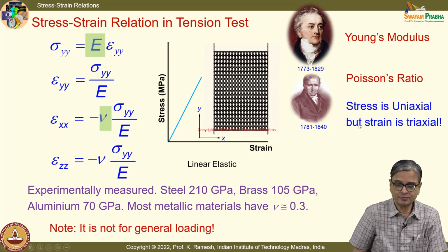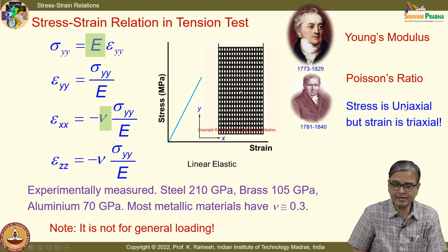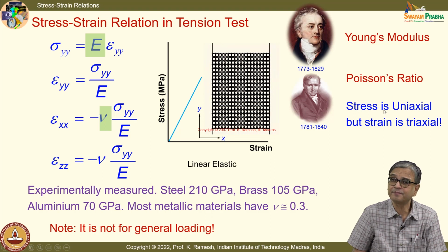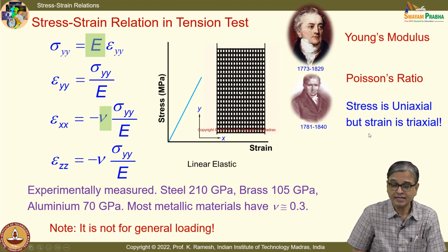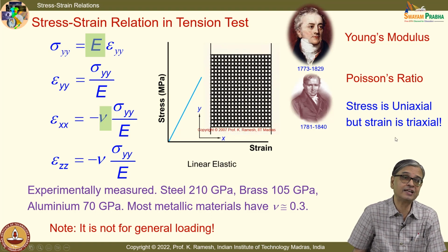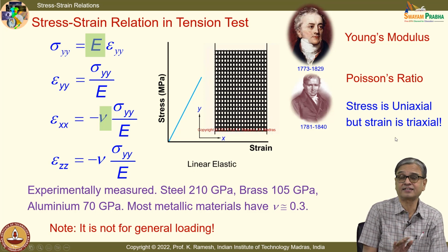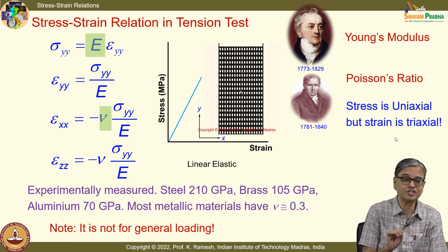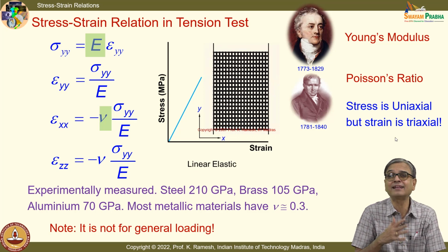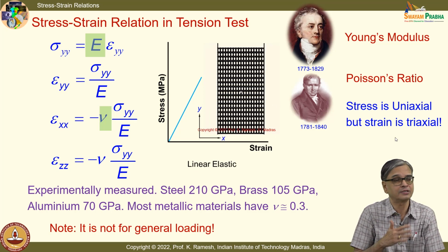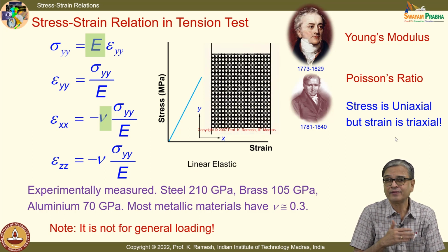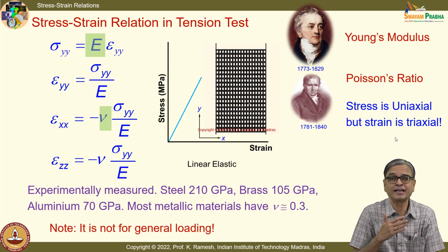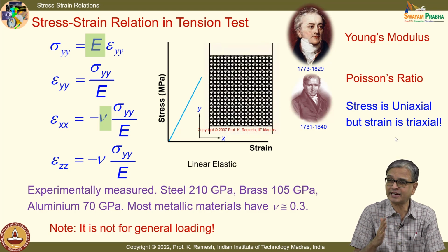So, I want to emphasize you can apply uniaxial stress comfortably. A uniaxial stress gives in general strain as triaxial. It may appear trivial, it is not trivial. People do not get this in the first level course. You have to appreciate when I apply stress, it can get deformation in all the three directions.